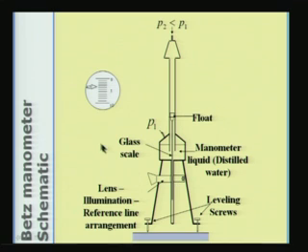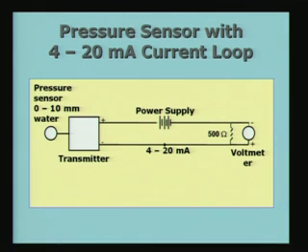So, you see that the delta P can be measured with very good resolution. It is supposed to be possible to measure, for example, up to 0.02 millimeters of water column. So, this is a very standard equipment which is usually found in laboratories where wind tunnel work is done. The next one is a more interesting case.